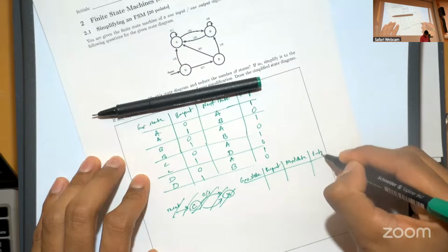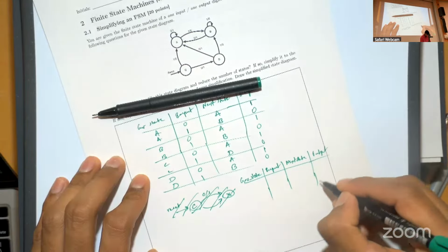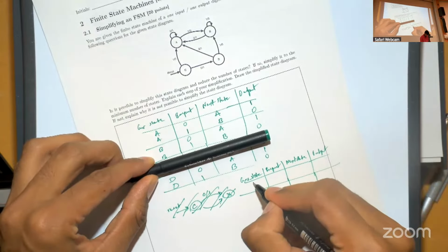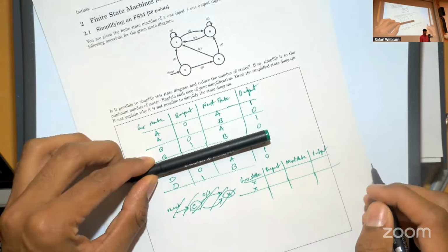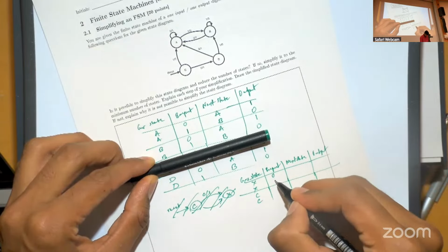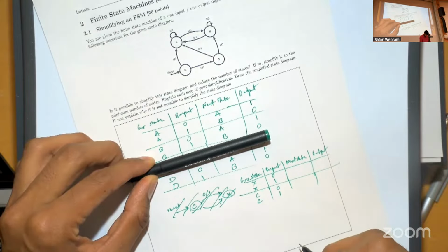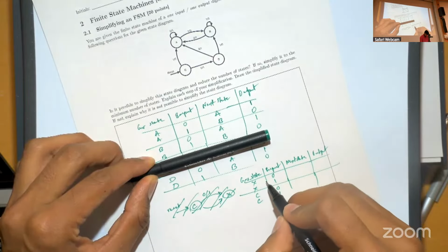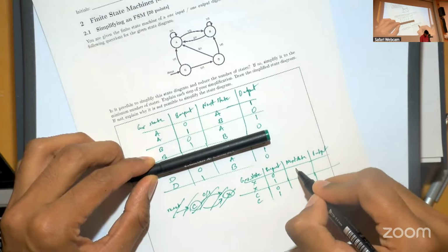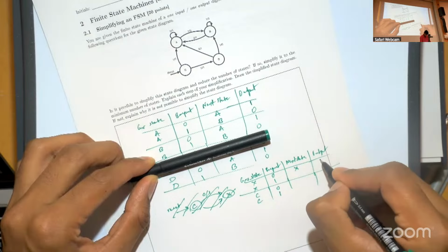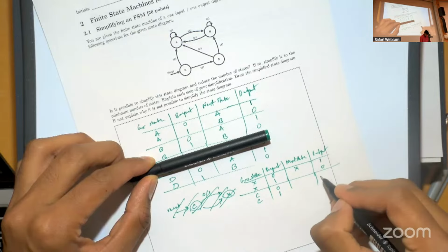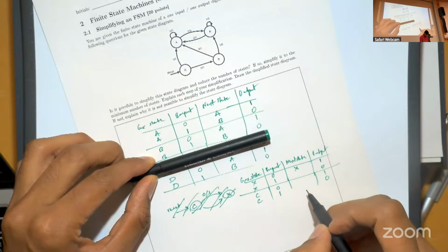And you have the output, okay? And we saw that we can decompose this down to 2 states. Let's say the new state is called X, okay? And we retain the C. And you have your inputs, 0, 1, 0, 1. When you see, for this state X, an input of 0, you stay in the same state, and you have the output 1. Your output is inverted for all cases. Let's fill that out first.